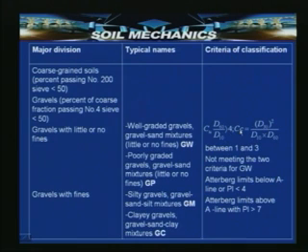So, Cu greater than 4 and Cc in the range of 1 to 3, then the mixture is well graded gravels, gravel sand mixtures, little or no fines, GW. So, the gravels where the coarse fraction passing number 4 sieve is less than 50, with little or no fines, is called GW.